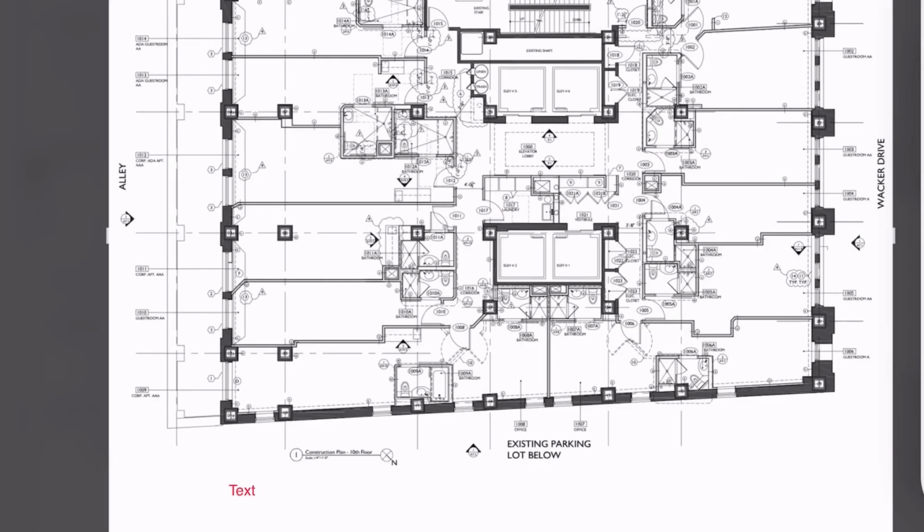This is to show you guys how to mark up your drawings and add the information with regards to the fire ratings of walls. What we typically do is show these little lollipops on the walls, and identify that the wall is a certain type of wall type. Like I'll say this is wall type A, and maybe there'll be a different wall type, maybe this one is wall type B or something like that. And then we'll ask you guys to just simply type it out, instead of drawing. We don't need the whole drawing, we just need you to type it out.